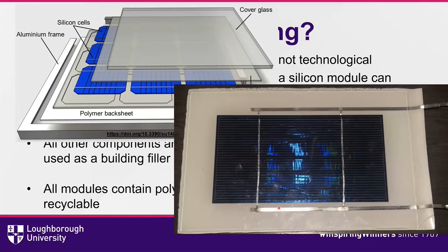And then you've got the metal bars that you can see. They're a silver color. It's actually copper, but it's copper which has been covered in a solder material. So the idea is that you can solder those wires, the bus bars, directly onto the cell quite readily. But the material itself in those metals is primarily copper. And then you've got a glass cover sheet as well. The whole sandwich is put together and then laminated using essentially a very large version of the sort of thing that you use for laminating paper. It goes to slightly higher temperatures than that, but the concept is very much the same.